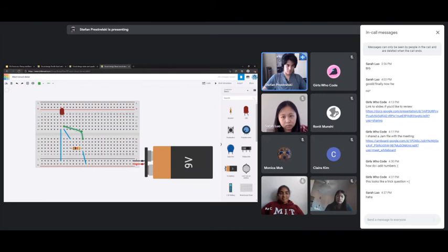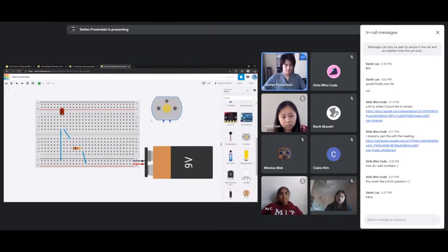To get rid of the short circuit, and you can see the LED is now completely fine thanks to the magic of Tinkercad. If I delete that wire, everything goes back to normal. If I add the wire back in, we fry the LED. I can also demonstrate what happens with this DC motor. I'm gonna move this lamp and move the LED out of the way real quick, and demonstrate what happens with just this motor.